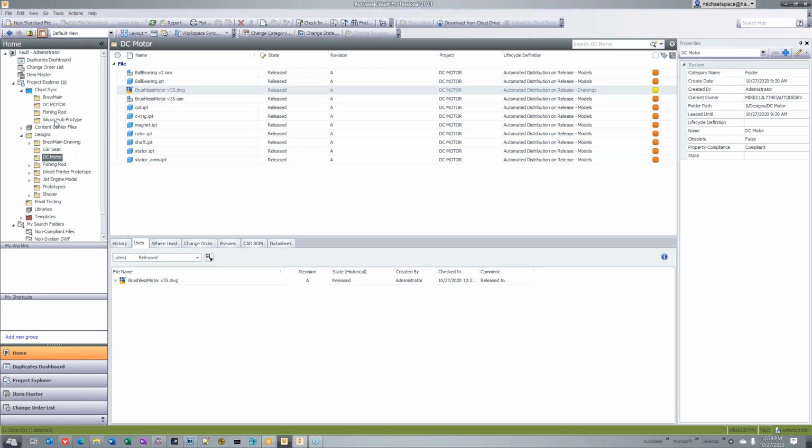Next question, Mike, is can you sort where the file goes based on the file name, like a part number? Yes, absolutely. Without getting too geeky, I could show you scripting, but essentially what my script does is it goes to the vault and says, give me all the properties of the file. And I say, the new folder name is the project name.